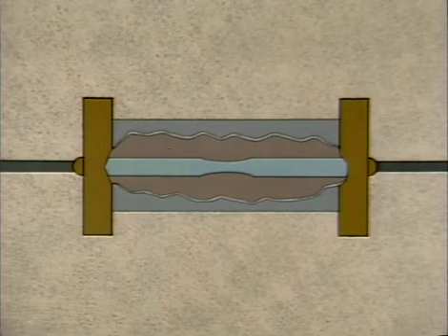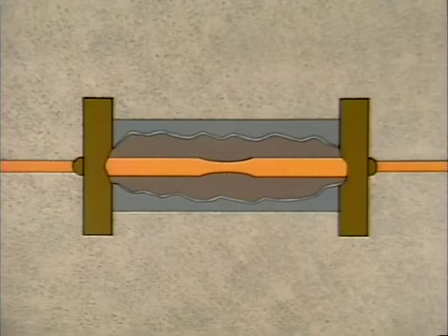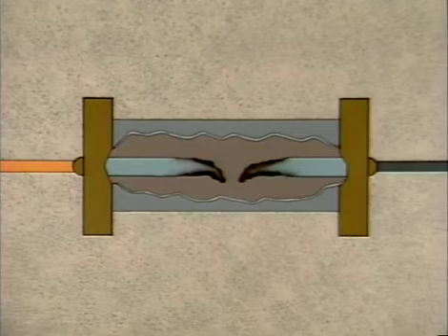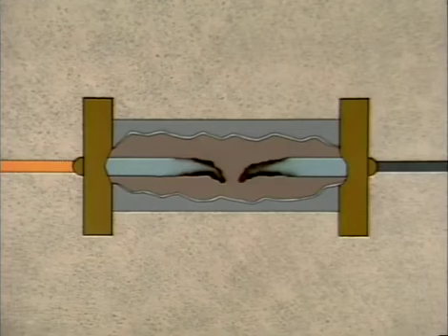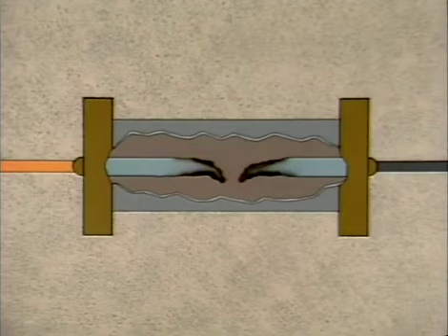If a fault develops in the circuit, current increases, creating heat. When the current exceeds a safe level, the metal link inside the fuse housing melts. This opens the circuit and stops the flow of electricity, de-energizing the circuit. De-energizing the circuit prevents the high current levels from damaging system equipment.